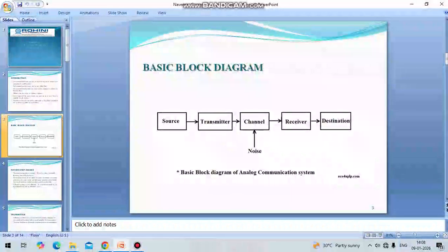The receiving end is also based on the type of medium. In case of a wireless medium, antennas will be used to receive the electromagnetic waves, which will be converted into an electrical signal, and the signal is processed using the demodulator and decoder. In case of wired communication, the signal at the receiving end will be an electrical signal. The signal is passed through the detector as well as the demodulator for processing and analysis, and it reaches the destination.